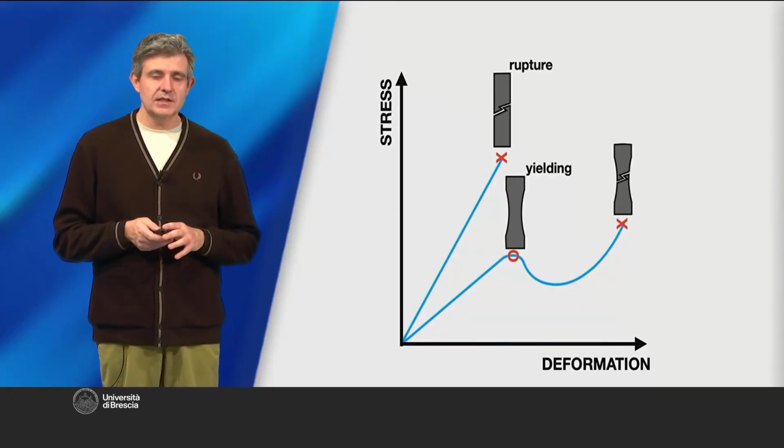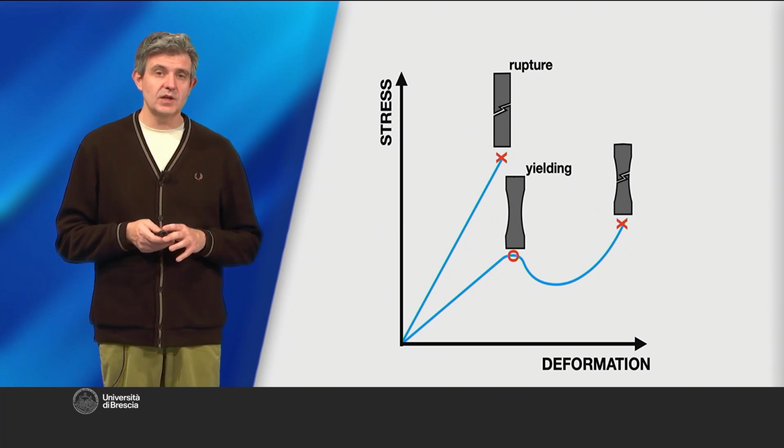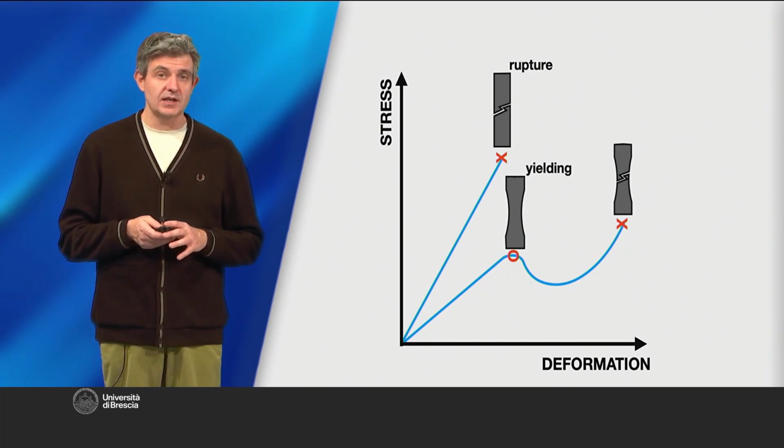This maximum stress is an intrinsic property of the material, and it can be determined experimentally. It represents the stress beyond which the material fails, which can happen in two ways, either by the piece breaking or by it entering the plastic deformation range, resulting in the loss of its mechanical functionality. In the first case, we call it breaking strength, while the second one is called yield strength. Both of these parameters are measured as the force at which failure occurs, normalized to the cross-sectional area of the sample, and are typically expressed in megapascals.